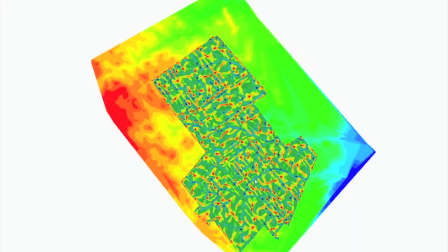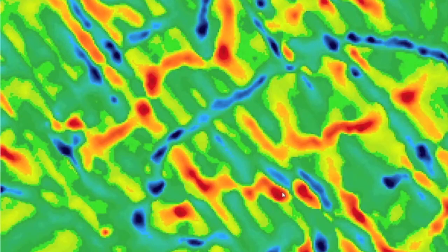The first step in a water management plan is to have a topography map made of the field, farm, or entire watershed area. The topo map can identify the low-hanging type fruit that can be corrected, usually at the least amount of cost. Look at the watershed map of our farm.